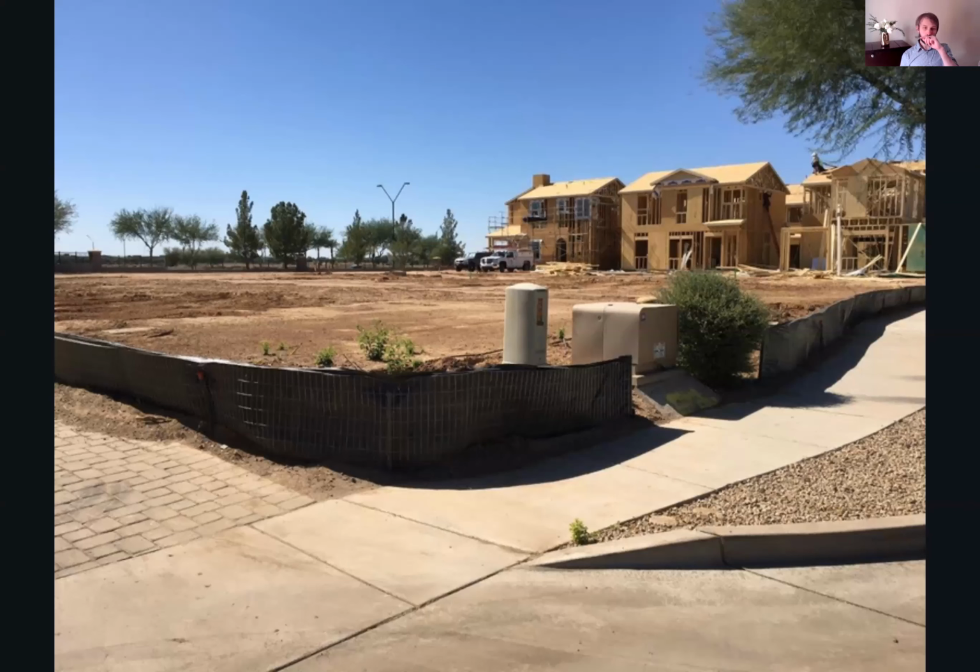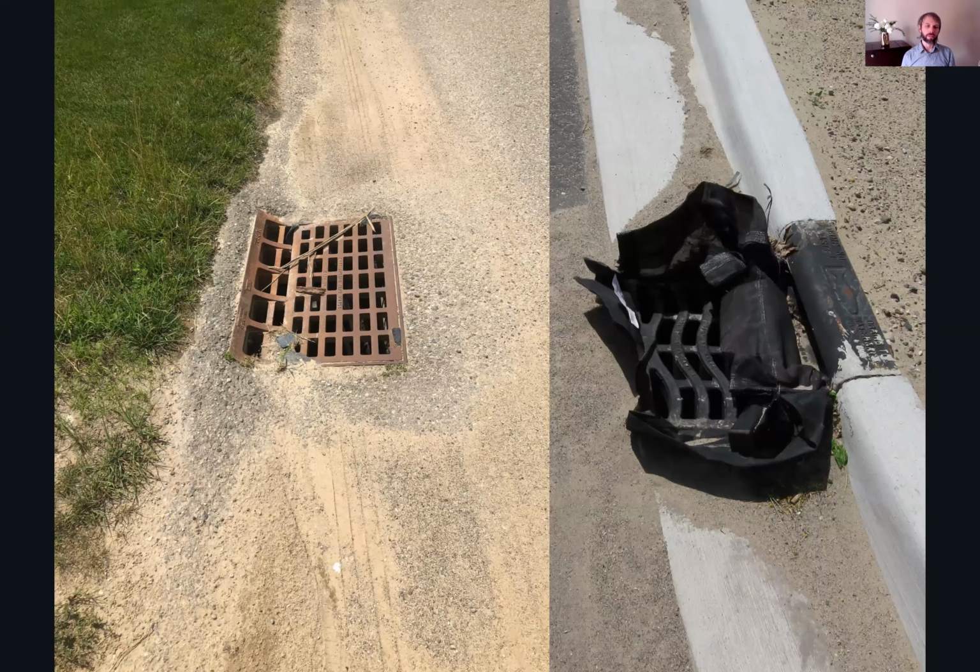All right, in this next section, we're going to talk about the construction and design process from a place standpoint. Obviously, putting in your plans, stormwater pollution control prevention, and then having on-site quality control in place to make sure these things are maintained. We see netting collapse all the time when big rains come through. You want to make sure you're not destroying the stormwater discharge during your construction practices. Here on the left is a bad example of a sewer we found that didn't have the proper netting in it. On the right, here's a good example where we've got that proper netting in place.